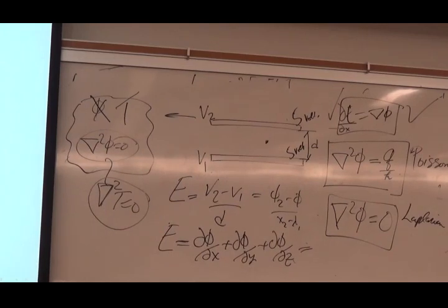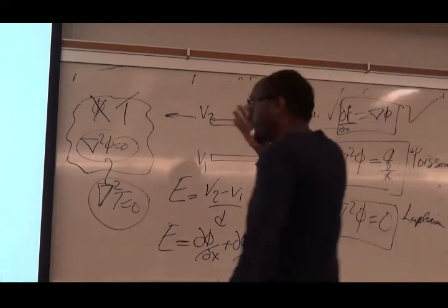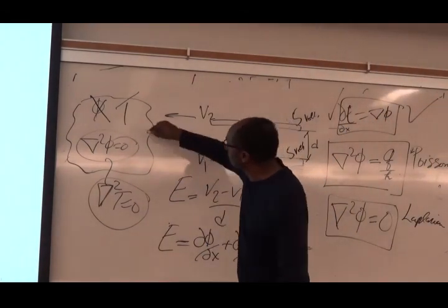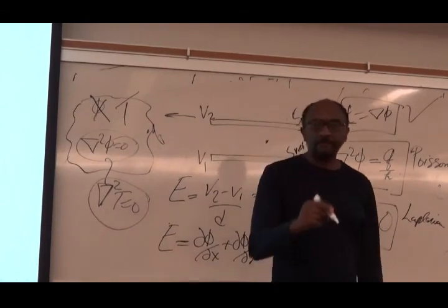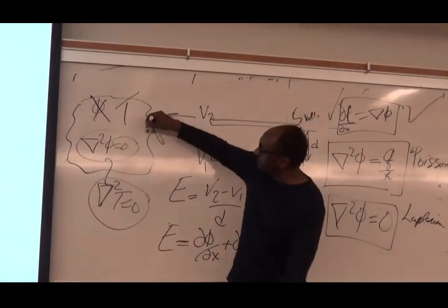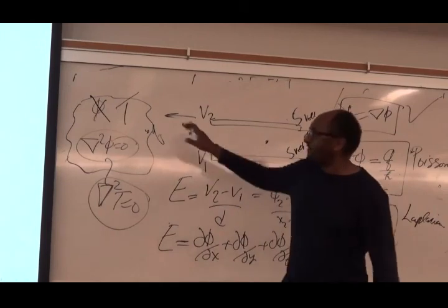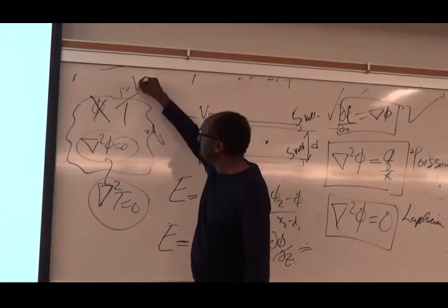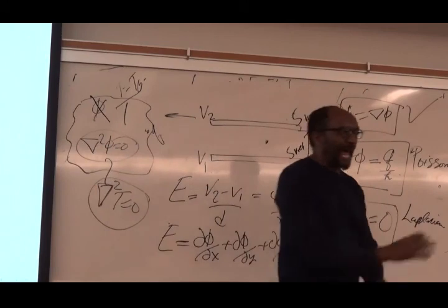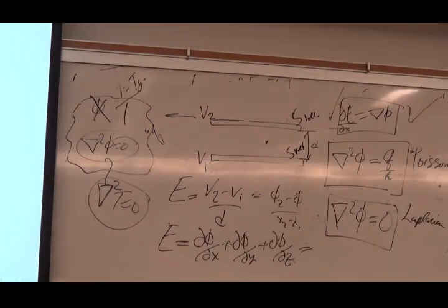There is no source term. I'm not adding potential as I'm solving. So you're looking at it in an instant, right? Basically. Actually what it means is I don't have source terms. So I could have, for example, a heat source. I have a boundary condition and I'm holding this to some kind of T. T is equal to 0, I isolate that, but I don't have any additional heat source. Then the conduction equation is del squared T is equal to 0. And here is what is really beautiful, because essentially the same equation applies to physics.